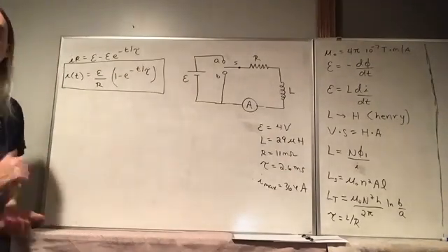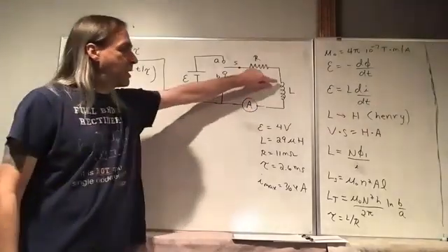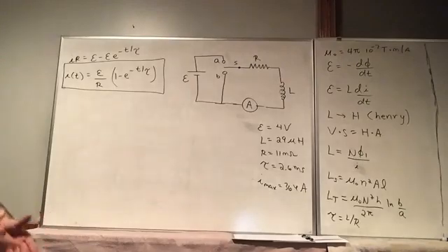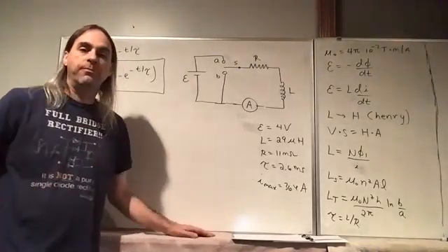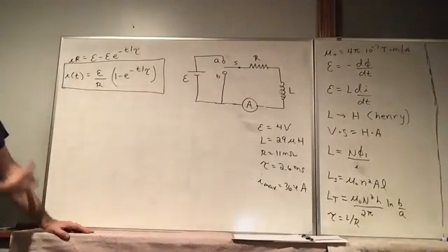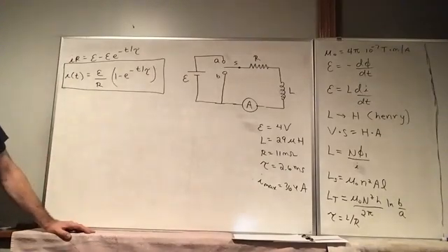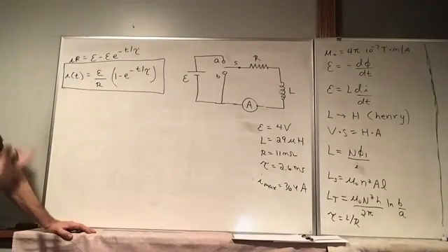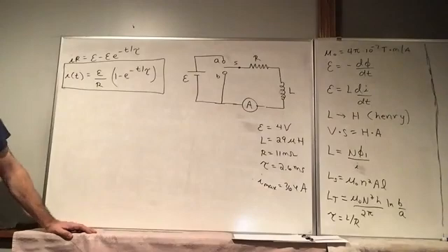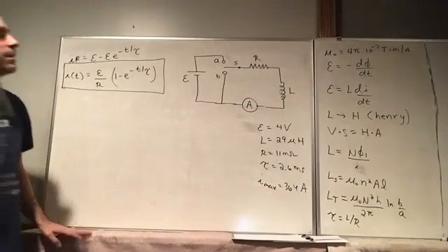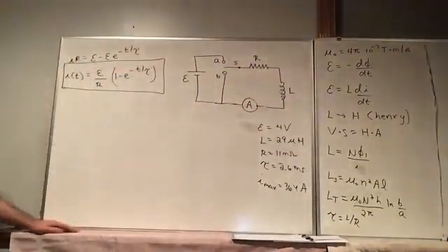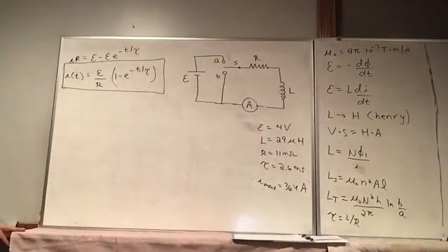That's a very large current, which means there's going to be a pretty strong magnetic field in that solenoid. The magnetic flux through that solenoid is very large. However, the voltage drop across it is 0 because the flux is constant now. So what matters is how quickly that flux is changing, not what its actual value is. So now that we have a steady current flowing in here, this inductor has no effect at all. We're at 364 amps and it's holding steady.